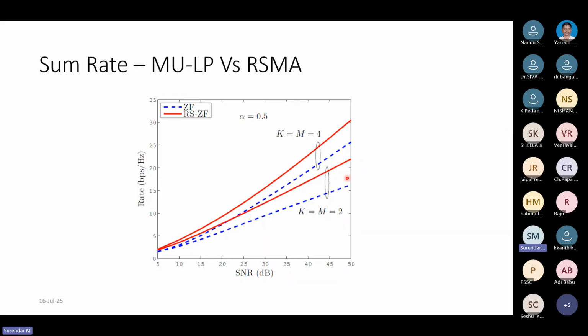They have differentiated with respect to antennas because as we keep increasing the number of antennas, proportionately my performance will also be getting better and better. That's what they are trying to say, because increasing the antennas increases the complexity. So we are supposed to know: is there a merit in increasing the number of antennas? Is it worth it to have more antennas for transmission? Yes, when you are using RSMA or SDMA, it is definitely worth it. But with respect to NOMA, it is not.